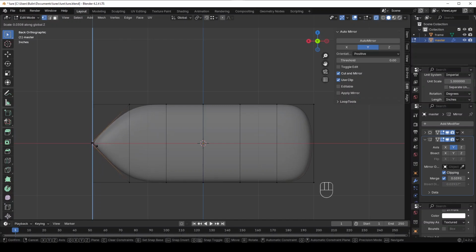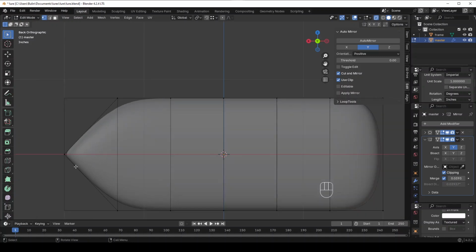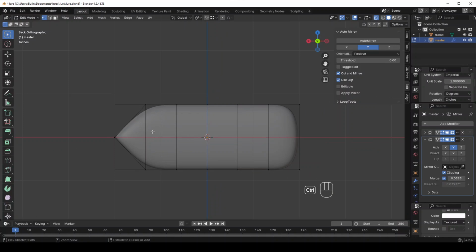You don't want to make it too sharp, because what you'll find when you're applying epoxy, if you've got a real sharp edge there, epoxy has a hard time staying on these sharp surfaces. The surface tension wants to pull the epoxy, later, whenever we're finishing the lure, away from real sharp edges. That has a little bit of a curve, so it may be okay, but I like to have a little bit more roundness. So I'm going to hit Control Z to undo.